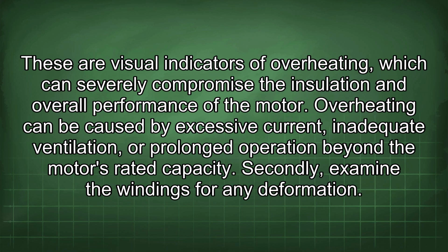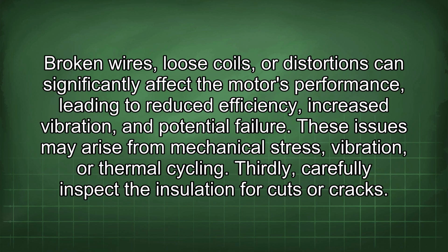Overheating can be caused by excessive current, inadequate ventilation, or prolonged operation beyond the motor's rated capacity. Secondly, examine the windings for any deformation. Broken wires, loose coils, or distortions can significantly affect the motor's performance, leading to reduced efficiency, increased vibration, and potential failure. These issues may arise from mechanical stress, vibration, or thermal cycling.